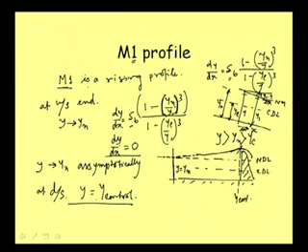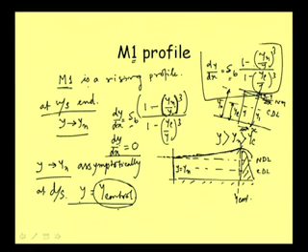what is happening at the downstream end. So, like that different other situations may come, but at upstream we are very much sure that it will be equal to yn, and it will just tend to become yn asymptotically, and at downstream point the control section depth will be defining the depth of flow profile, and in between from here to here, the flow profile is a rising profile. This will be a rising profile and the shape of the profile, what will be the shape of the profile? That will be governed by the equation dy dx, this equation.